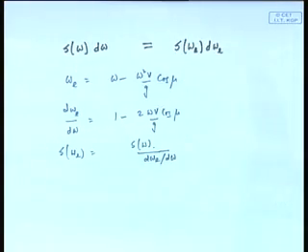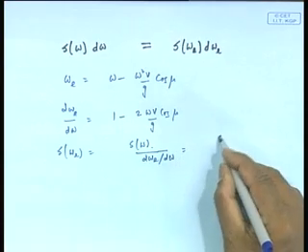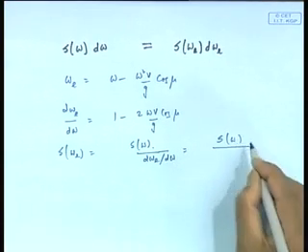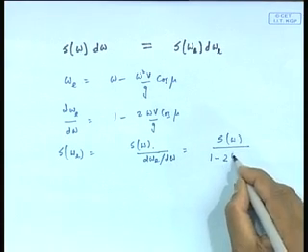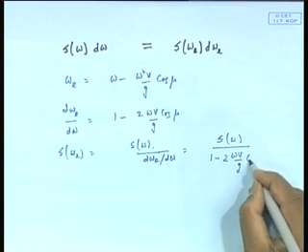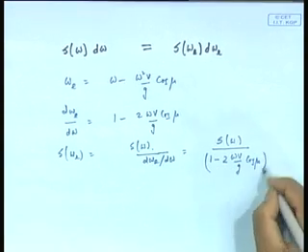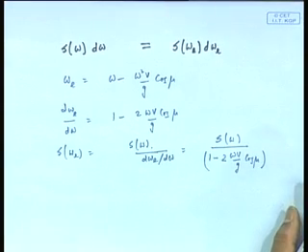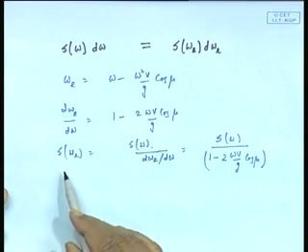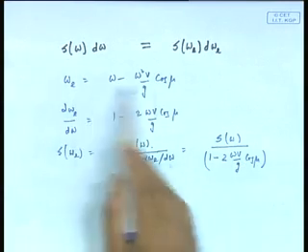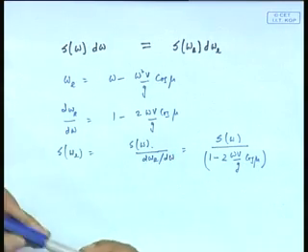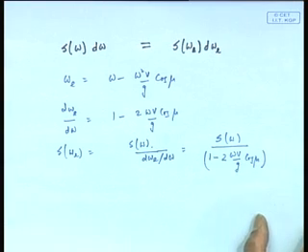You agree with that straight formula? So, this becomes... so you see you get this formula here and you get this formula here. So, it is now a simple procedure to transfer the absolute wave spectrum to what is called an encountered wave spectrum, that is, the wave spectrum seen by the ship.